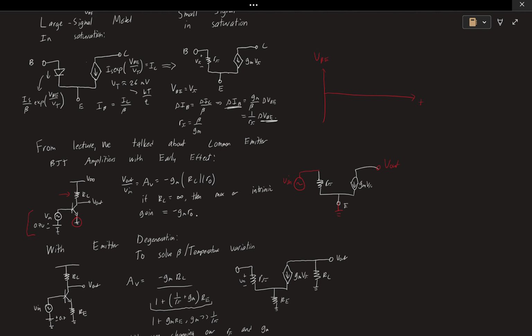So in other words, if there's no voltage change across some node or some element, then that's effectively a ground when it comes to AC analysis, or not AC analysis, sorry, our small signal model. Okay, so 0.7 volts doesn't change in time. So what that means is, hey, it doesn't change in time, it has a change in time of 0, and 0 is effectively, well, our ground. So it becomes grounded. And kind of a similar idea with the RC.